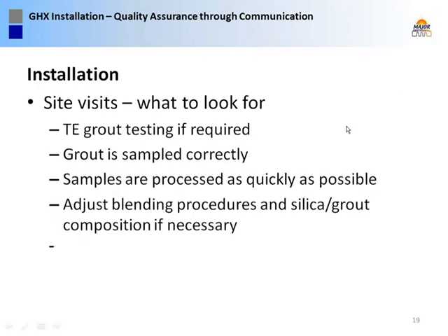Also, if you do have thermally enhanced grout spec, we find a lot of times drillers, we've had several jobs recently, the job was nearly done, they hadn't even sent in their first grout sample to be tested. So we get out there with the cattle prod and make sure that on that very first batch in particular, that morning the sample is taken, and that afternoon it's on FedEx to whoever we're having doing the testing, like GeoPro or whatever.